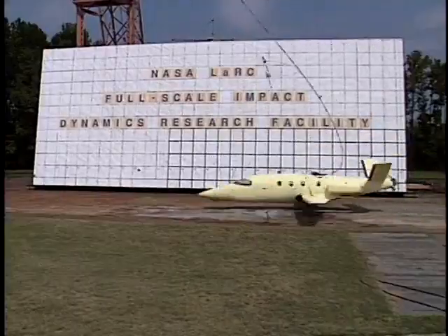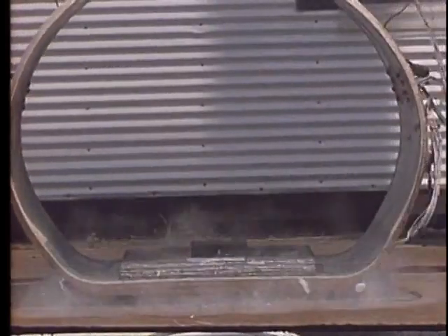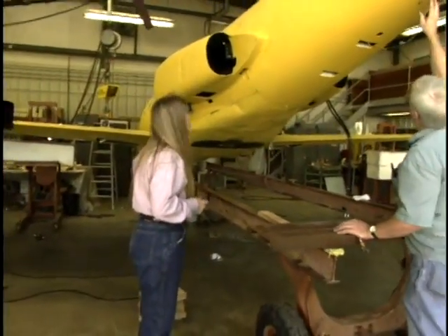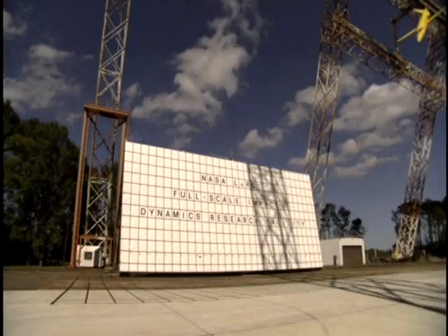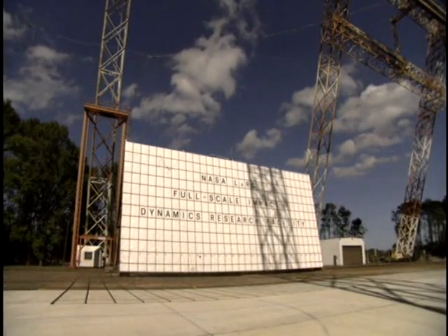Yes, in 1994 we tested a graphite aircraft called the Lear Fan. When the original aircraft was released from the gantry, it was extremely rigid and nothing crushed. According to the crash test dummy data we collected, only one of the 6 passengers survived. So we used that data to design a new energy-absorbing, or crushable, subfloor. It would be like putting a bumper under the floor. Then we built and tested small sections of different subfloor designs until we had the best design. A second Lear Fan was modified by installing the newly designed subfloor and tested. The results showed that the new subfloor improved the Lear Fan's crashworthiness by reducing the forces on the passengers.